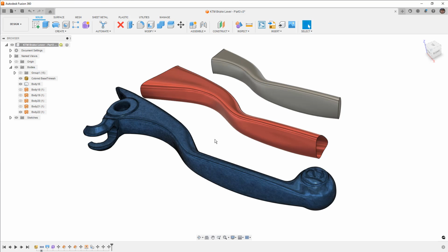So because of that, transitioning from either the freeform surface or the mesh section sketches to some of these more prismatic features is just not going to end well. The transition between those features down to the surfaces is just going to be bad quality. There are going to be issues with surfaces where if we try to thicken them or offset them, they're going to fail.